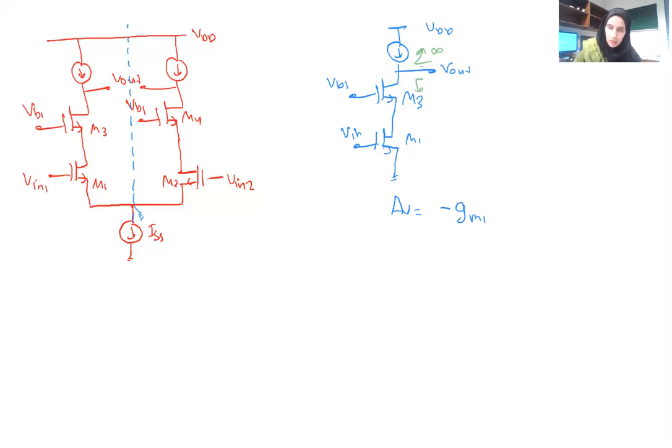And if we look down, we see a cascode having an impedance of GM3 Rout3 almost, Rout right. So now the gain will be minus GM1 times the output impedance, which is just going to be GM3 Rout3. This is GM3. Okay, so this is the gain of the amplifier that we are having here.